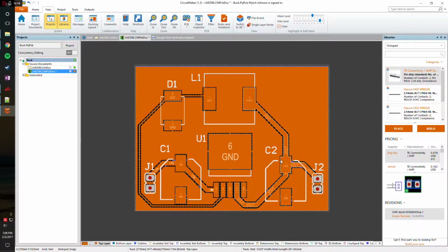A Gerber file is a standard PCB format. It's basically a series of files that explain what's happening in each of these layers down here. So the top layer, the bottom layer, the outline, all the way to the end, where we get to the paste and the overlay. That's like these little indicator type of things. That's what that is. So it's basically a series of files.